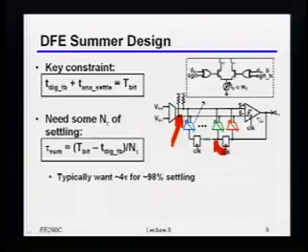Okay, so that's actually a very important point, which is one of the, let's say, subtleties, but really beauties of this structure: in terms of the current, I'm really adding all the currents linearly. So the subtraction I want to do in terms of the signal processing is correct. The only thing is that afterwards, I'm going to distort it through some nonlinear impedance at that node. Which means your voltage amplitude could be smaller, right?